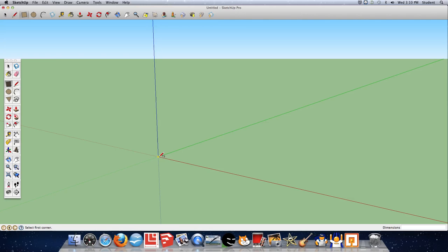To begin my rectangle, I'm going to click on the origin, and then take my hand off the mouse. I've clicked once, and I'm going to start dragging the mouse out to the right. My hand is now off the mouse. I'm not touching it at all. You'll notice that the box is still open. It's just a lined box. Now, with the keyboard, I'm just going to type in the number 5, a comma, and 2.